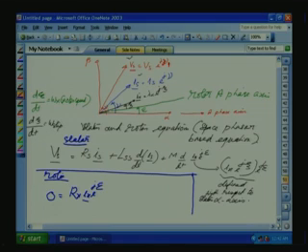That means this IR underscore is a space vector, it has a magnitude and angle defined originally with respect to the rotor axis. Now, multiplying by e raised to j epsilon, the whole thing is defined with respect to the stator A phase axis. Plus rotor self inductance, mutual plus leakage, LRR into d by dt IR.